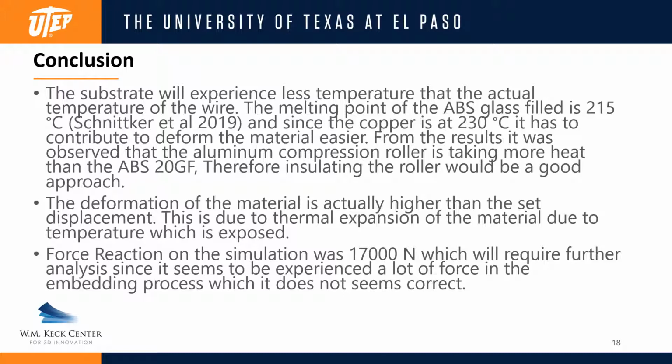Looking at that, the actual heat is helping deform the substrate. And again, the reaction force in the simulation was 17,000 newtons, which will require further analysis, since I don't think the tool is experiencing 17,000 newtons. Again, this is my suggestion, but it might be correct too.